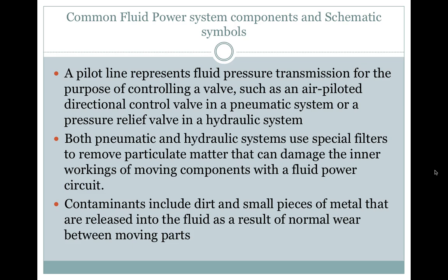Both pneumatic and hydraulic systems use special filters to remove particulate matter that can damage the inner workings of moving components within a fluid power circuit. Contaminants include dirt and small pieces of metal that are released into the fluid as a result of normal wear between moving parts.